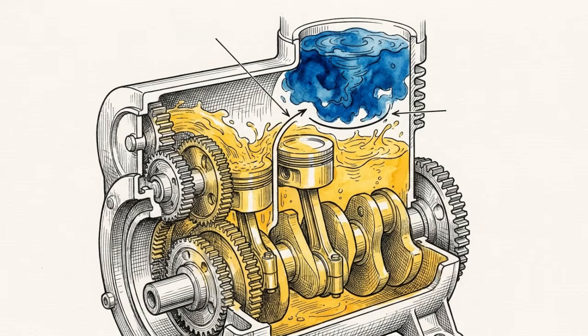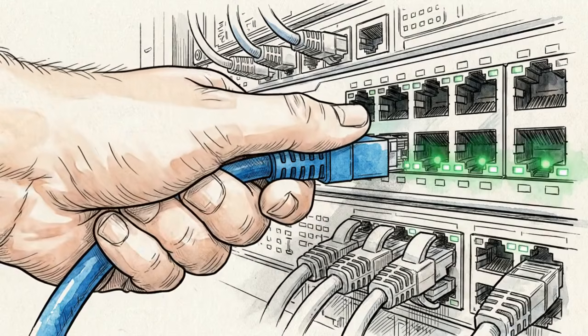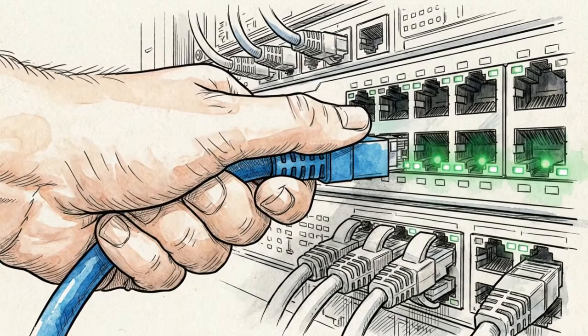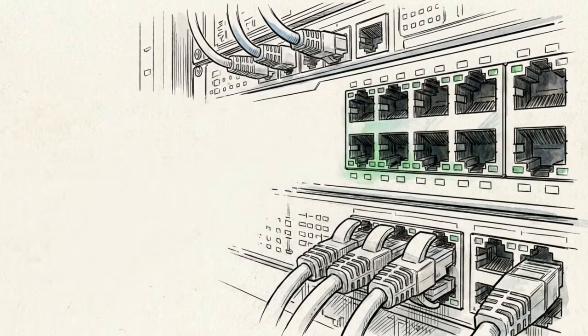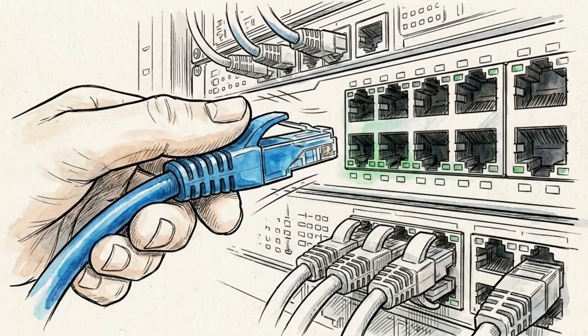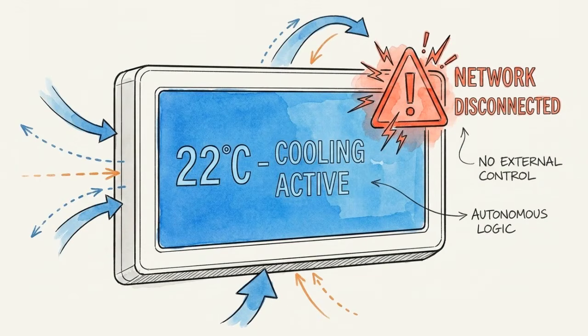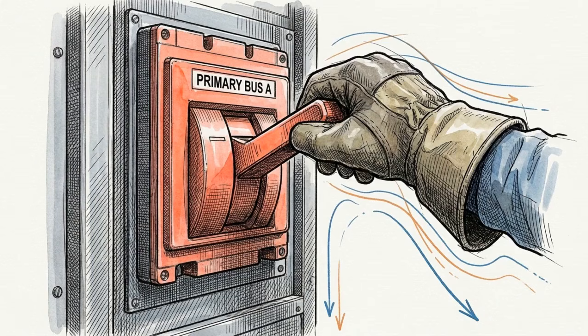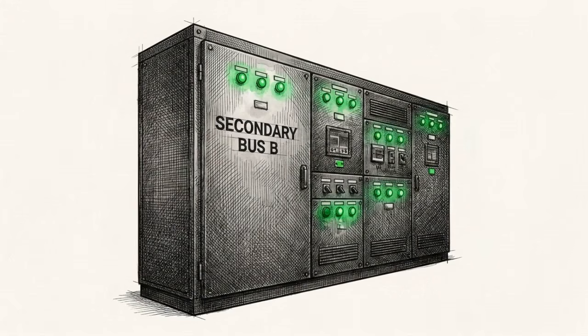inverter spins up. Next, the commissioning team simulates a controls failure domain by severing the connection to the central BMS gateway. This proves that local autonomous logic will continue to sustain the critical cooling duty without central supervision. To simulate a power failure domain, engineers drop the primary A bus breaker. They must confirm that the independent B circuit completely picks up the thermal load without requiring human intervention.